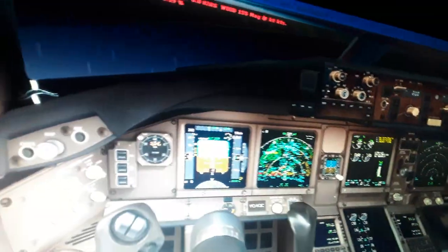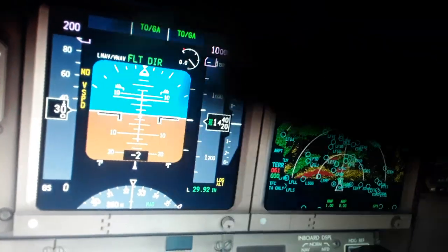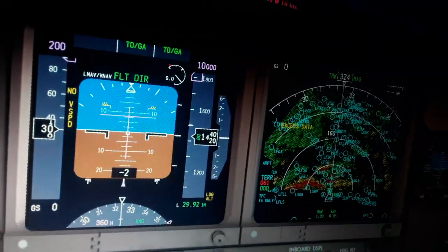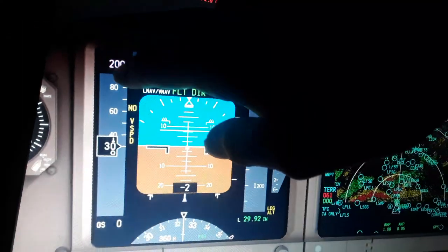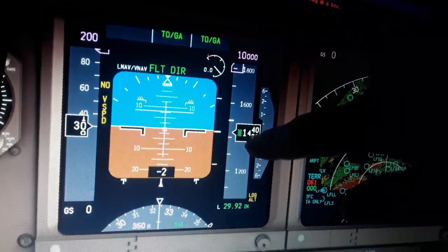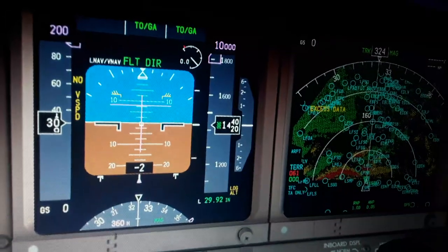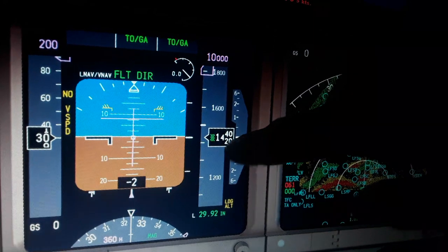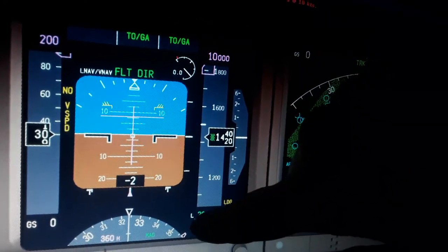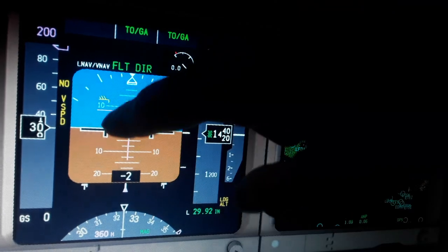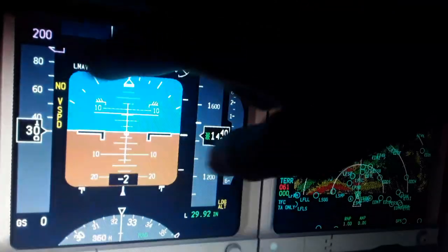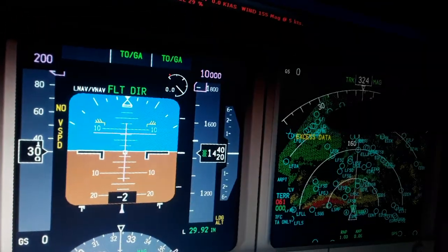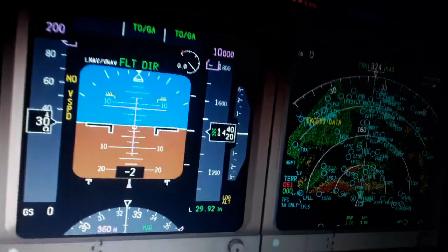the primary flight display. That displays the indicated airspeed. The minimum airspeed indicated is 30 knots, the ground speed is 0. The airspeed selected from the autopilot flight director system panel. The altitude selected, the target altitude selected from the autopilot flight director system panel. Also, here is the elevation of the aircraft above sea level, 1,430 feet. The barometric altitude setting of the outside atmosphere, magnetic heading and track, and also this is the altitude indicator, the laser gyroscopes calculate this, the rate of turn of the aircraft in positioning.